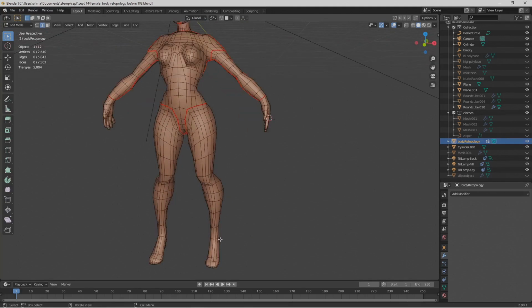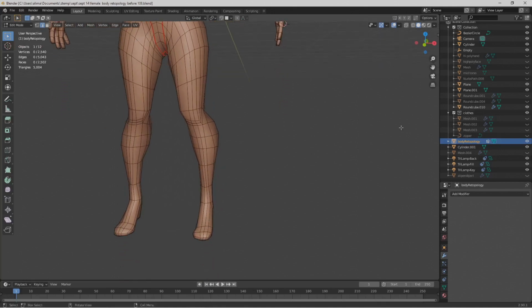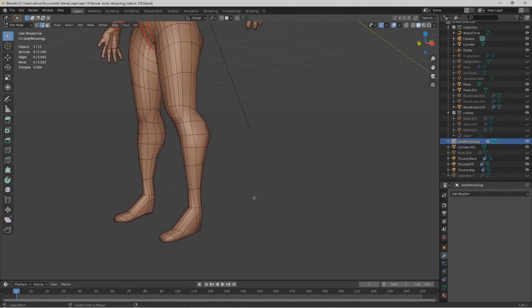Okay, I'll zoom in. Select the hand to the upper right. I'll hold Alt as well as Shift to select here, as well as here. Select here, as well as there. Then I'll hold Control, press E, select Mark Seam. Left click to try to deselect.